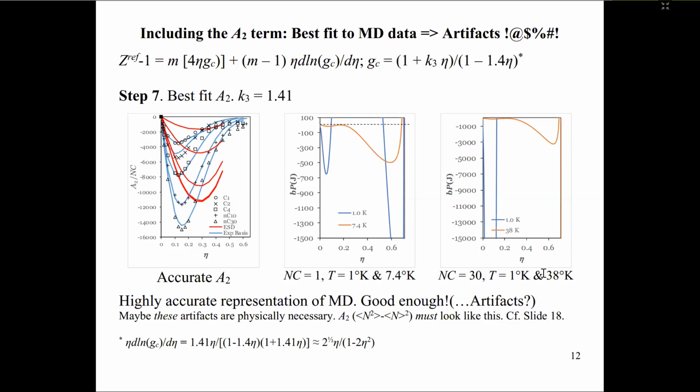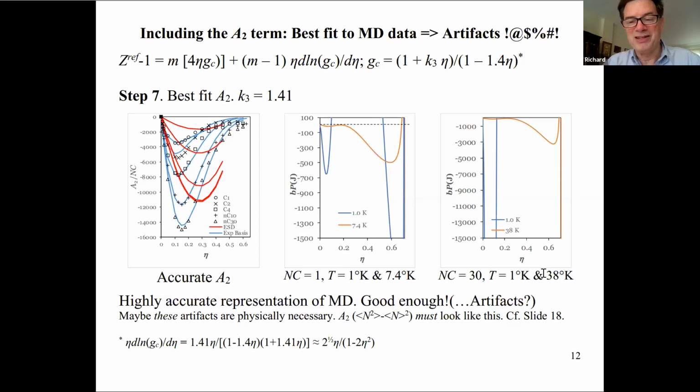That might be good enough to satisfy any eutectics that might occur with propane and everything else like that. And then you could argue, well, helium, hydrogen, are we really working in a range where we've got 99% helium and any appreciable amount of liquid propane?